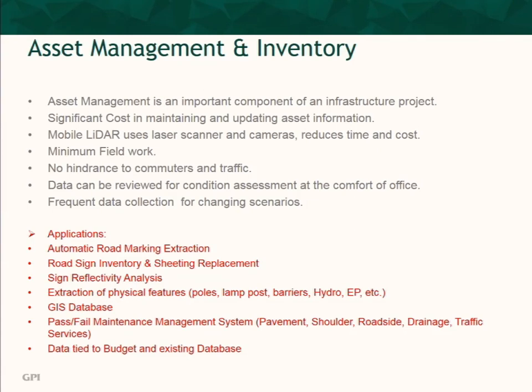And of course, reflectivity studies and analysis, where at night we can shine a light and give them reflectivity values for all of these signs. And we're collecting physical features, planimetric features, from poles to lamps and barriers and curbs and gutters and catch basins and edge of pavement. You name it, we collect it with these point clouds.